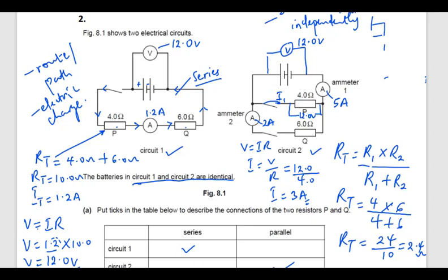If you look at this circuit, the 5 amps here, which is the current flowing through the circuit, when it gets to this junction, is split into 2. One passes through this route, the other through this route. We just calculated 3 amps for this one, and the other is 2 amps. On getting to this junction here, the 3 amps and the 2 amps merge together to form the 5 amps. Remember, conservation of charge.